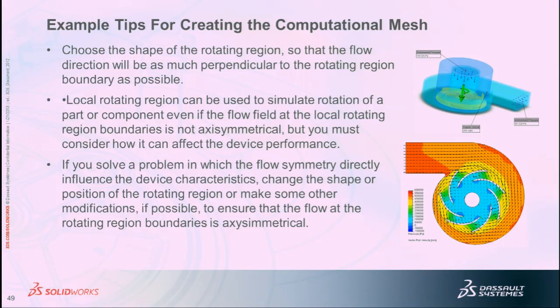And you have to select it as the rotating region. So all the cells within that rotating part, that feature that you disabled, will have that extra body force term of rotation, that angular velocity that you put in there. And then you can also select it in your local initial mesh command to further refine the mesh, because the velocities tend to be quite high in those regions. So that's what these slides are talking about.